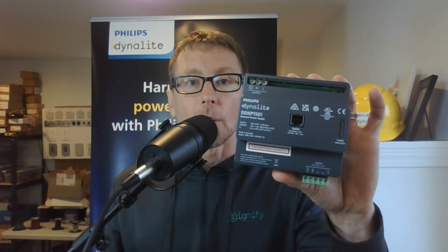So step one is to wire up your device on the bench. We've got our sensor here, we've got our PC node, but that's not enough because the USB on the PC node is not going to be enough to power that sensor. We also need network power. So either grab yourself a power supply or a spare load controller to get everything fully powered up.